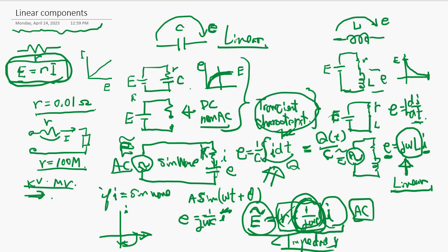The same thing, phase shift, but it's 1 over j, the other way around for the capacitance. Okay, so remember this. This is very important. In the AC system, capacitor and inductance become linear elements, just like a resistor, simple linear elements. Why so important? We talk about that next.